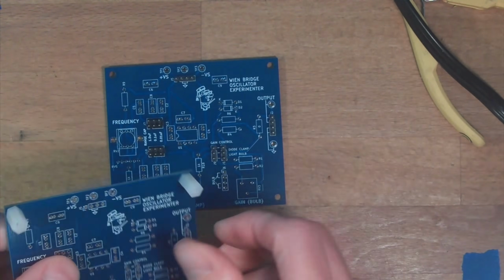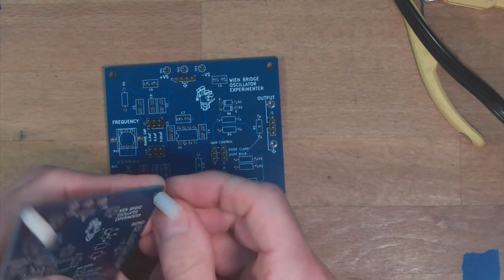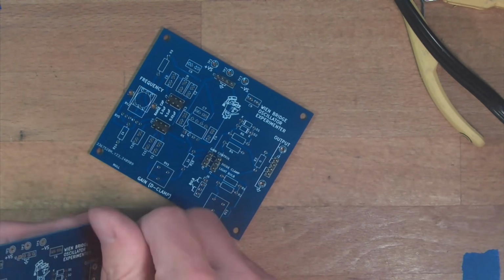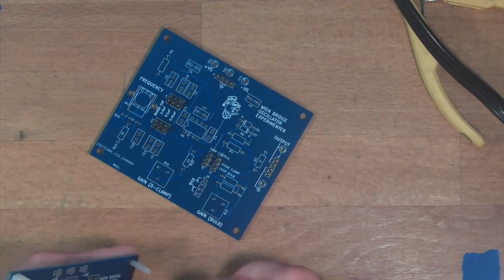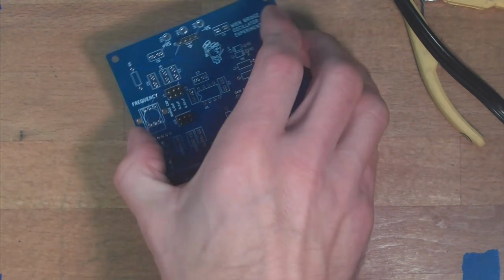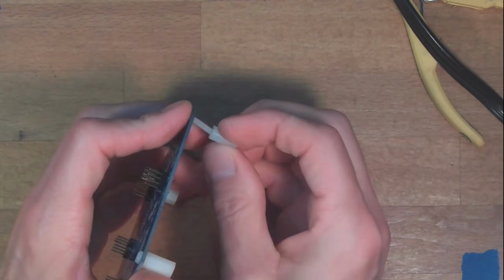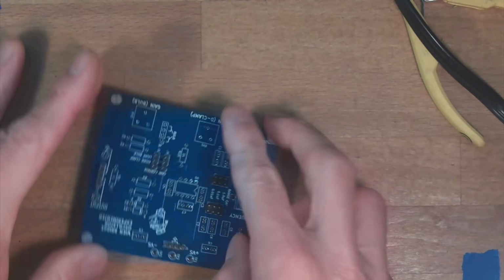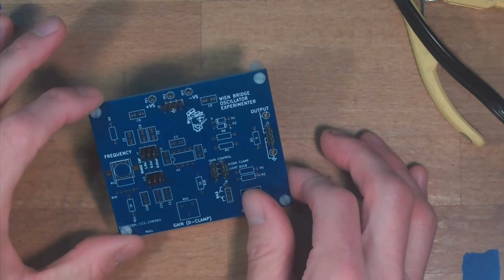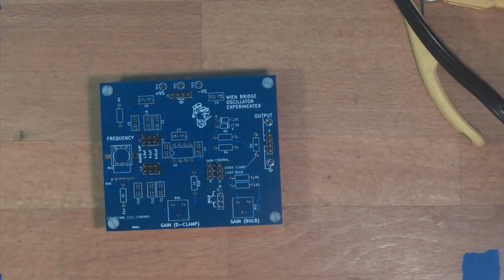Okay, great. So then the next thing that you do is, let's see, I guess you can either use little standoffs to hold things up. You know, I'm going to do that just to make other parts of this a little bit easier. Okay, so there's the jig. I can put that away. All right, so this gives us a nice surface. I prefer soldering resistors and leaded components from the top sometimes. So let's get some of our other components in here.